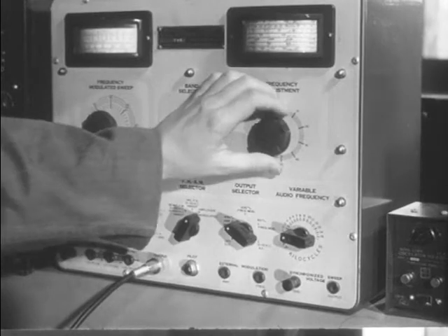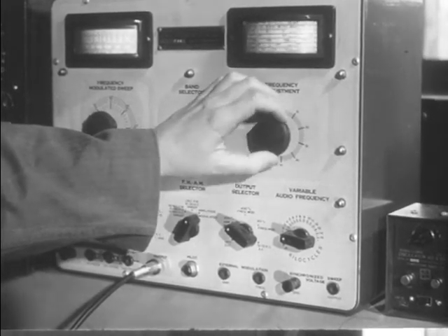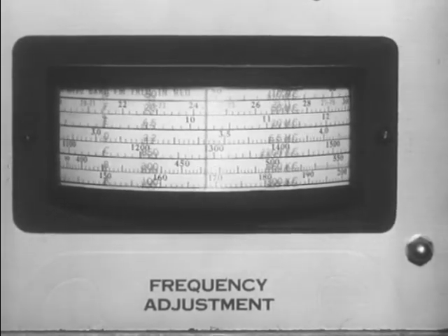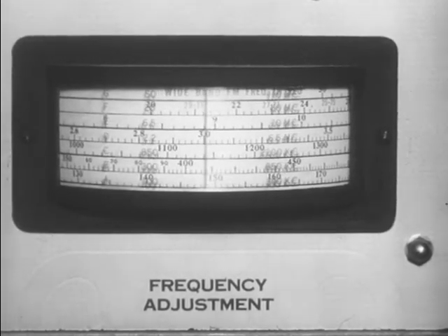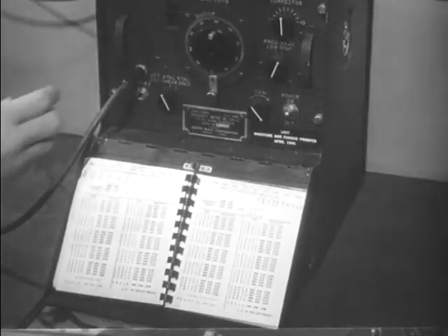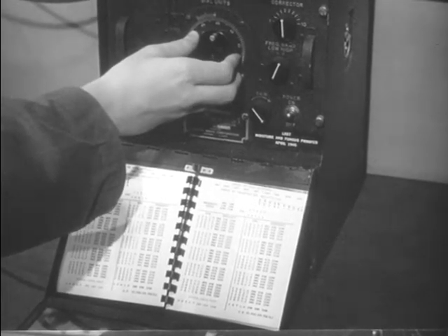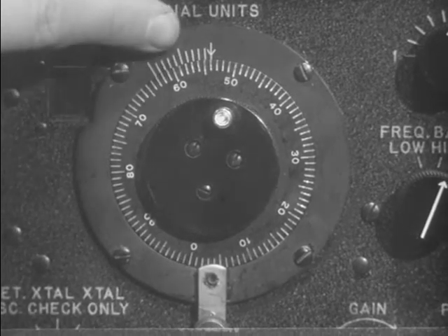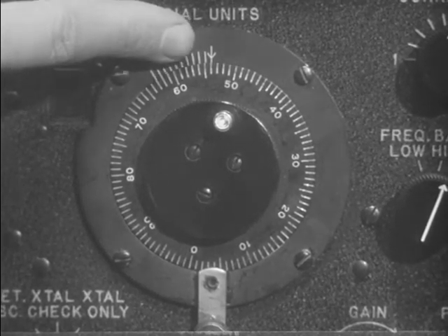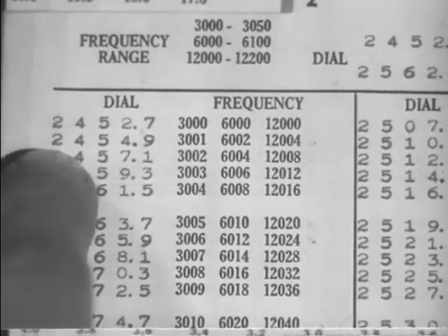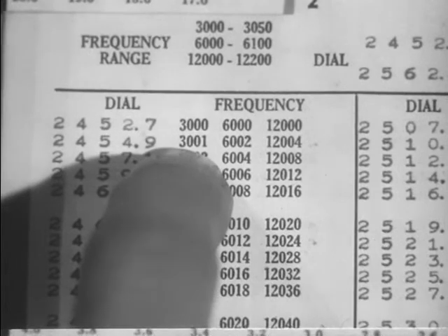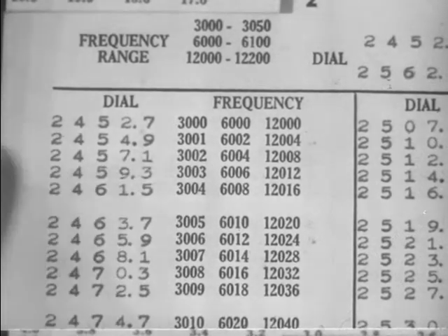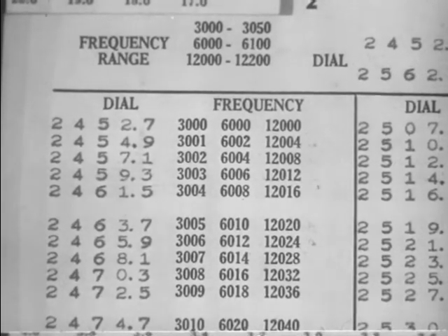The signal generator, through jarring or other mishap, may get out of alignment. A frequent check of the calibration of the signal generator with the frequency meter is advisable. It is only a matter of sending out a signal on the generator which is received by the meter. The frequency meter is tuned to the exact frequency until a 0 beat is reached. If the meter and generator dial readings agree, the generator is in tune. A tolerance of 1 or 2% is allowable on most signal generators. Of course, this procedure must be accomplished on each band to check the accuracy of the entire range.